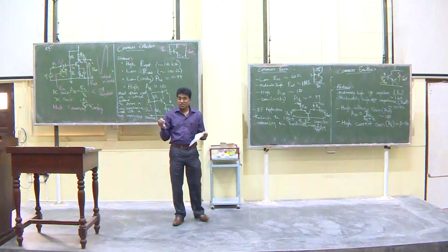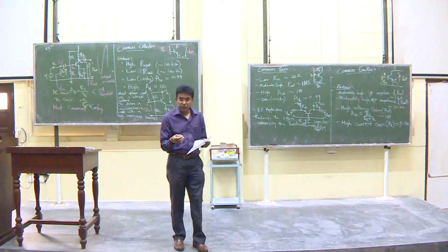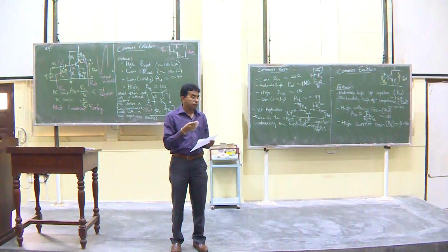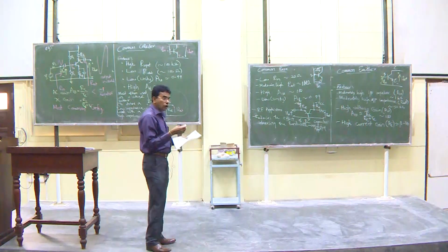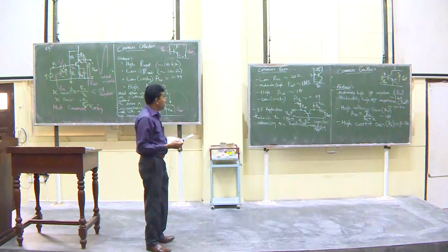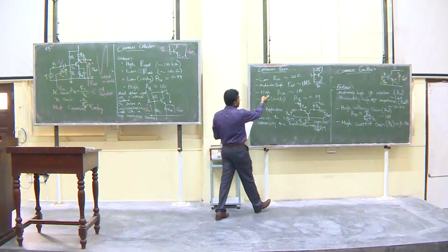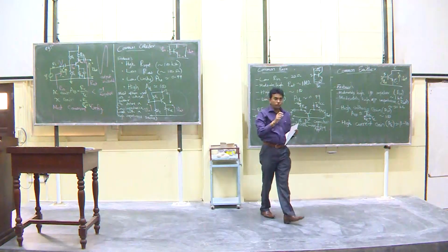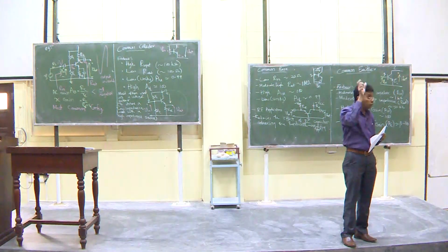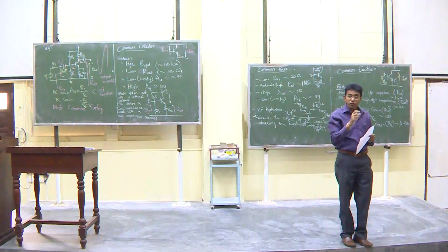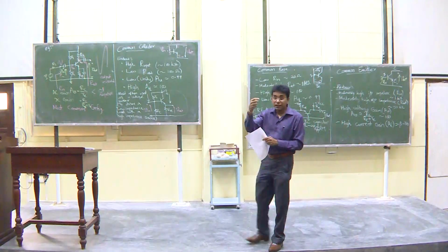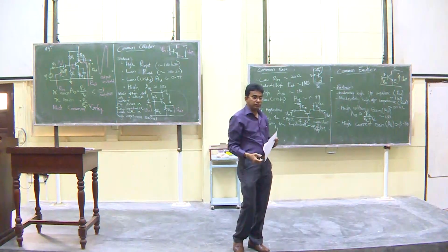Now, since this does not have any voltage gain, we typically use a common emitter amplifier stage after this to drive the load, because the output impedance is pretty high here. So, therefore, it cannot drive a load. If you try to draw a current, there is a voltage drop across this 1 mega ohm large resistor. So when you connect it to the load, we typically have a common emitter stage after this. Okay.